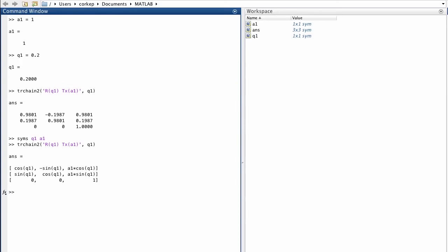Another thing I can do using the robotics toolbox is to import a model of a planar one joint robot, and I do that with this function mdl_planar1, for model planar one, and we created a new variable in our workspace called p1, and we can see it's of a serial link type. It's a robot manipulator type object. Now with this particular object, it's got a number of methods, and an interesting method is the teach method.